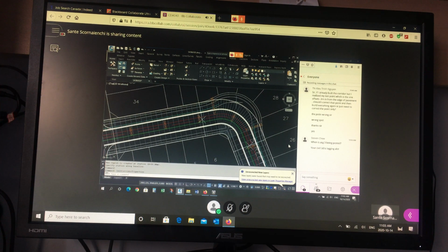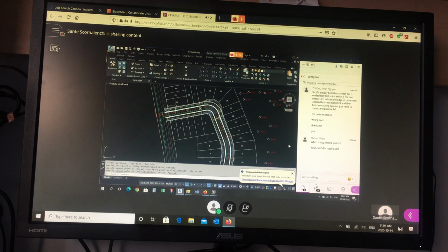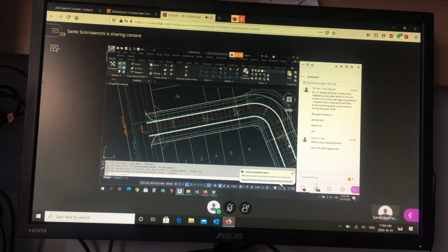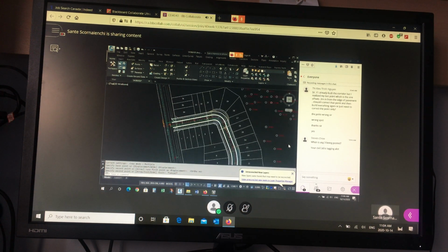So what I'd like to do, I'm going to go to my cross-section. I'm going to make a copy of this point here, just the assembly point. I'm just going to put it down here, a little bit lower. When you make a copy of the assembly point, it also copies the sub-assembly parts. If I was driving along my road in the direction of increasing chainage, 0 is here, 20, 40, if I look in that direction, my right hand is the right side of the road. So the cross-section going around the curve on the inside is correct, just like it normally is.